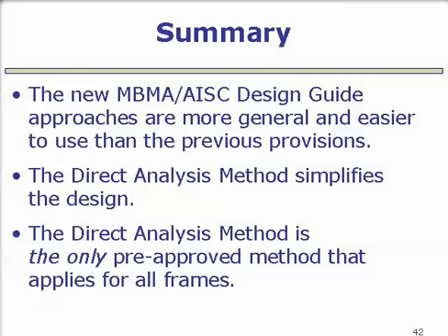In fact, if you have something like the modular frame that we're showing you here, because it's so wide, you've got a lot of gravity load that's beating up the frame there with all those leaning columns on the interior. And so, at least in some of your gravity load combinations, it's not uncommon with a frame like that to get side sway amplification that's larger than the 1.5 limit, where you're no longer allowed to use the effective length method.